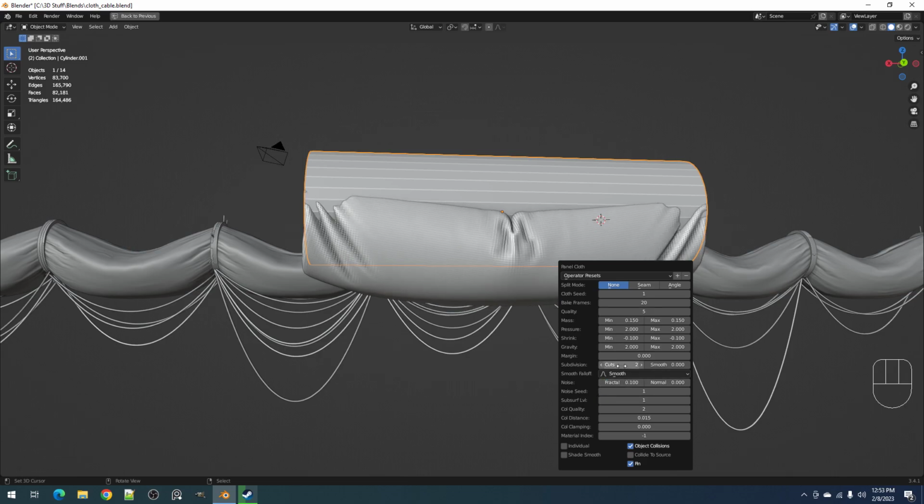The fractal is from the subdivision and the script. So mainly this is fractal noise, and normal means the fractal will extrude using the normal of the selected faces. Let's use that. And I've exposed this in orders because sometimes with weird angles of the faces, gravity and wind cannot produce the intended wrinkles, and you want those wrinkles.